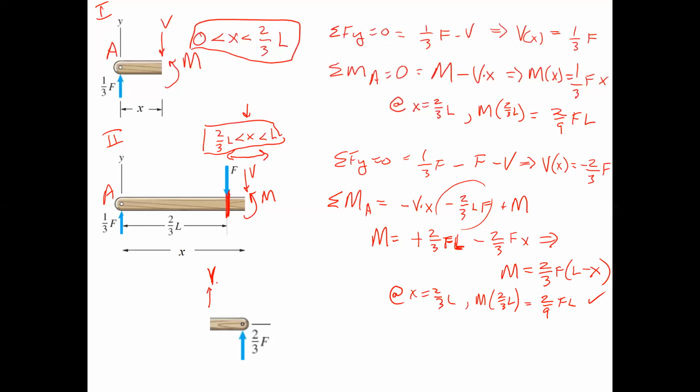Because it's causing the rotation. It's going clockwise. That's a positive shear. And which direction is the moment going to be? Clockwise or counterclockwise? To cause a U shape on that right section, it's going to be clockwise, right? In other words, we're bending it by doing that to it, and that's causing a U shape on that little section.